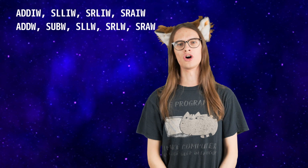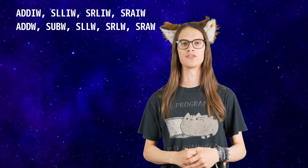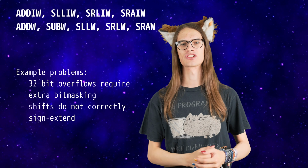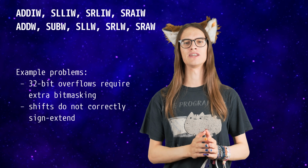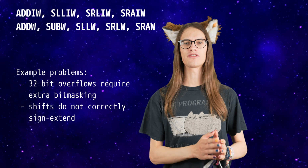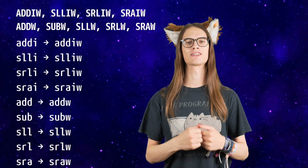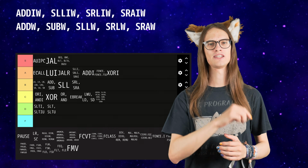All the normal integer operations use the full register size, so 64-bit for RV64. But operations on 32-bit values are still super common, and when we consider overflows and sign extension, the semantics are different enough that 32-bit arithmetic would quickly become complicated on 64-bit. Therefore, all the relevant integer operations get a 32-bit variant that retains the 32-bit semantics. Very useful, unfortunately a bit boring. C tier again.